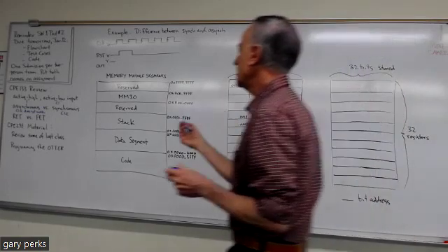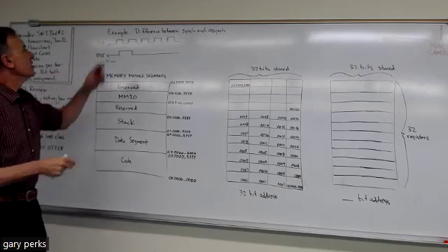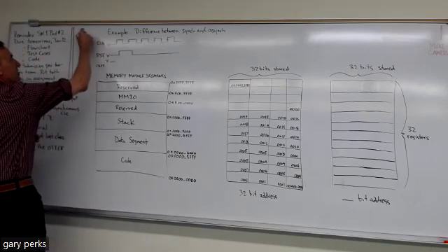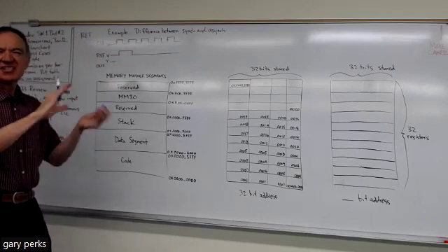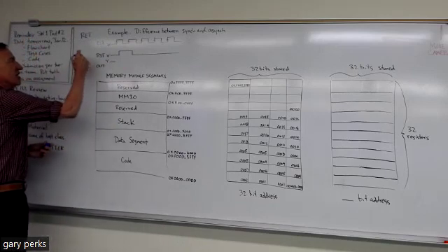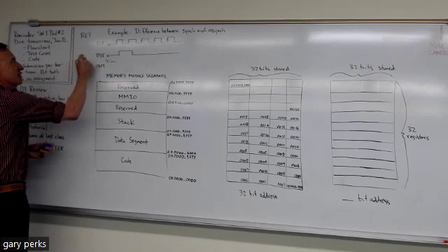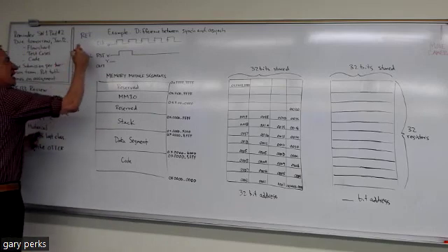Exactly. That rising edge is the transition from 0 to 1, right? At the time of that 0 to 1 transition, that's what we're talking about. And then falling edge is just the opposite, right? The time of this 1 to 0 transition. So in this example, let's say we have rising edge. That's why on the clock signal here, I put little arrows on the 0 to 1 transition, right? Because that's what we look at when we have a rising edge. So if we had an asynchronous reset that's active high,